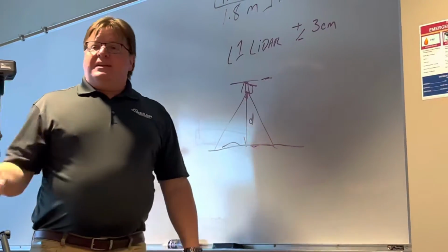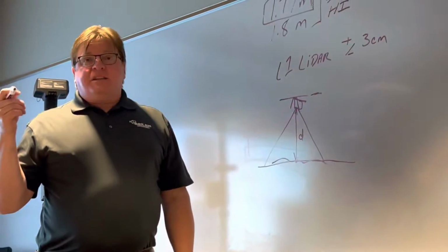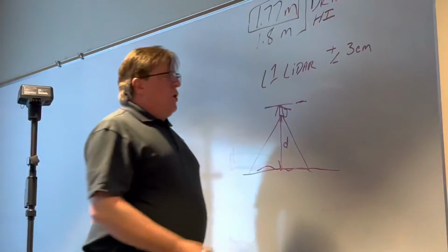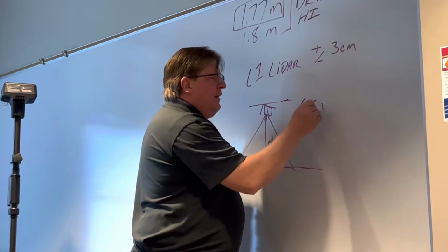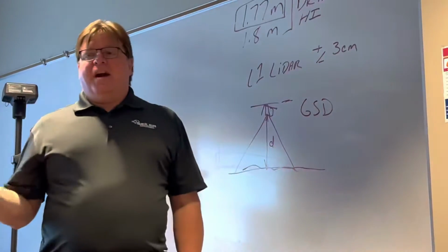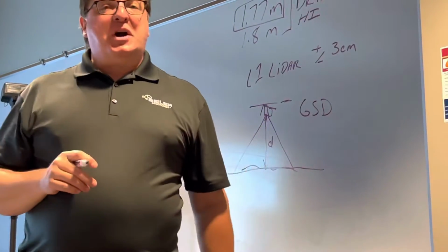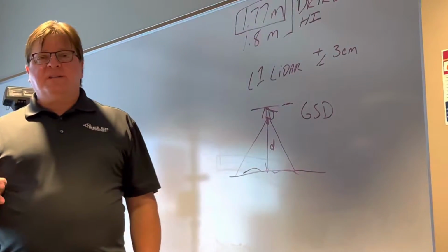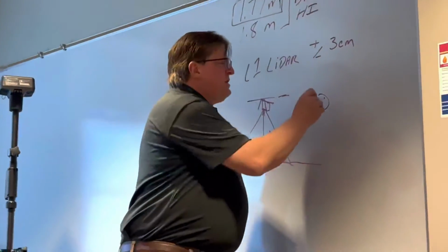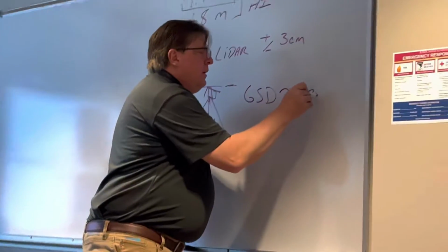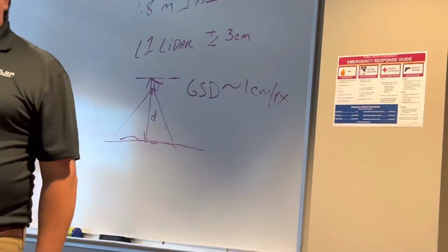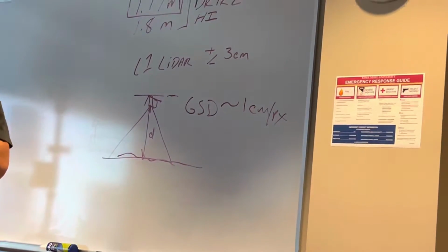The ground sampling distance is expressed in centimeters, all right? So if you have a GSD, we're gonna fly this. This is what we talk about all the time. For easy math, we like to shoot for a GSD of 1 centimeter. That's not set in stone, and that's per pixel. So centimeters per pixel is the GSD.